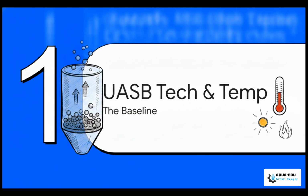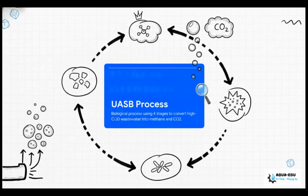This is the baseline for healthy granular sludge. So, before we can fix a broken reactor, I want to quickly reestablish exactly what makes a healthy UASB tick, right? What creates that absolute perfect environment for our granular sludge? At its core, the UASB process is this highly efficient biological engine turning high COD wastewater into biogas, mostly methane and CO2. The wastewater flows from the bottom up through that thick blanket of granular sludge, and this breakdown happens in 4 distinct stages: hydrolysis, acidogenesis, acetogenesis, and finally, methanogenesis.